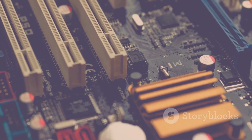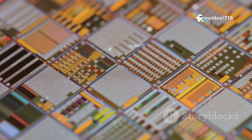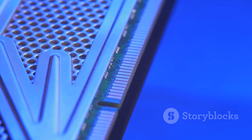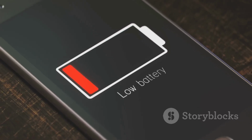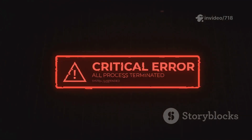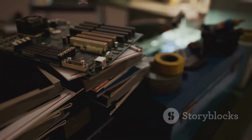It's a fundamental trade-off. The simplicity of the memory cell, just one transistor and one capacitor, is what allows manufacturers to pack billions of these cells onto a single chip, making DRAM incredibly dense and relatively cheap. This is why you can get 16 gigabytes or 32 gigabytes of RAM in your laptop. The downside, however, is this constant need for power and refreshment. If you turn off your computer, the refreshing stops, the charge leaks away completely, and all the data in the DRAM is wiped clean. This is why it's called volatile memory.